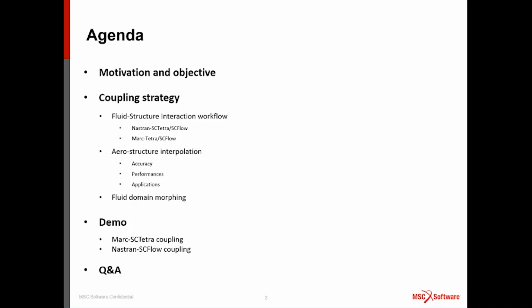Another important point is fluid domain morphing, because when we couple an FEM model with a CFD solver, we not only send information from one solver to the other, I mean loads from the CFD to the FEM model, and displacement with velocity and acceleration to the CFD solver. We also have to think about how the CFD domain is morphed. It is really important because as soon as we get negative volume issues, the CFD simulation gets stuck. So we have to avoid this. We have worked a lot on this topic, and I'm going to explain how everything works.